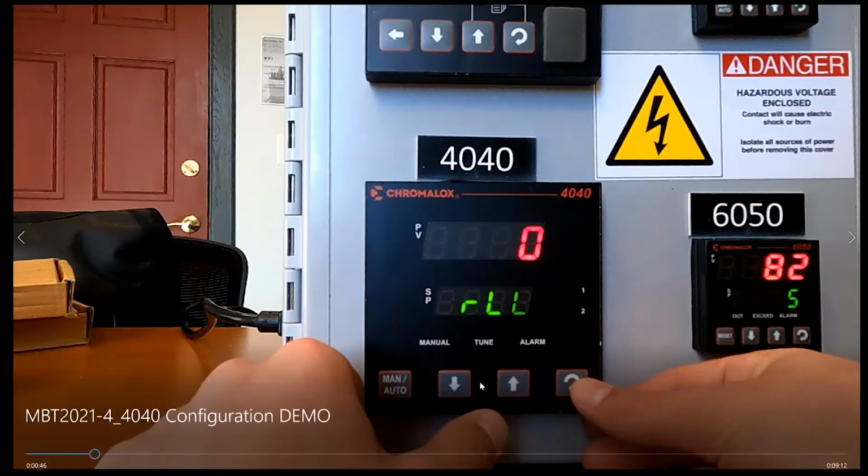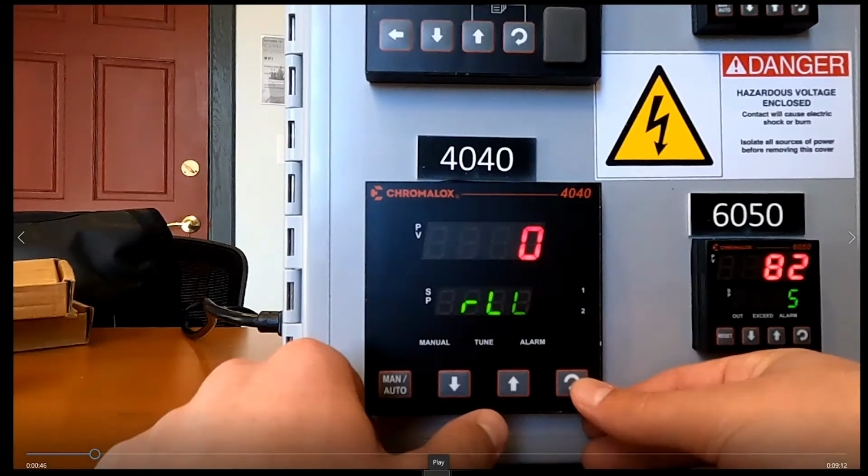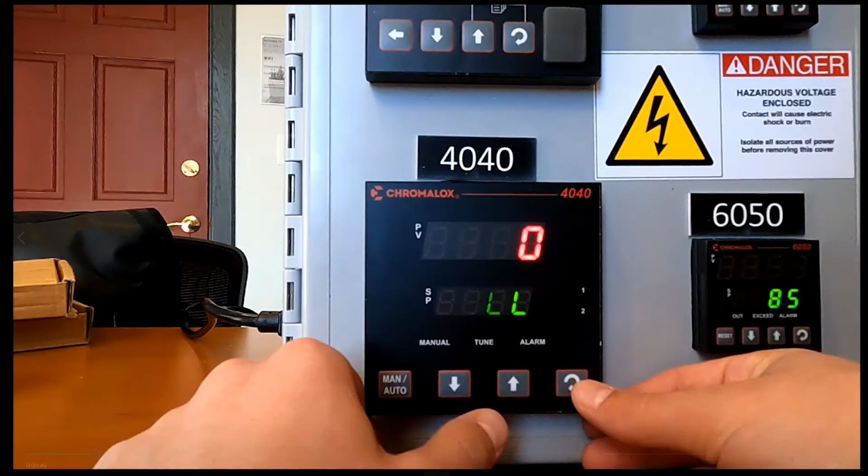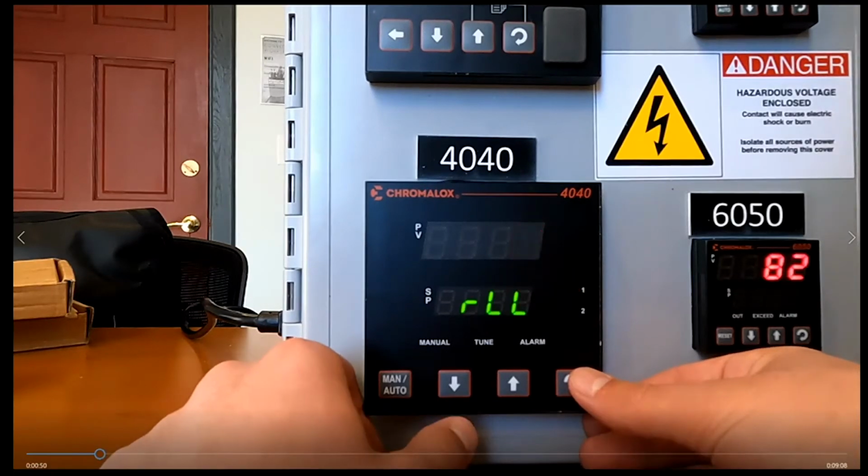So if you have a nice even number, it's going to be way easier to program from the customer side of things. If you're using a thermocouple and RTD input, then this has a little bit of a different function. Anything that involves spans later on, which we'll get into, will work off of this ratio. So a lot of it's percentage based. It's a lot easier to know what 10% of 1,000 is versus 10% of like 1,532, something like that. So that's what's going on there.